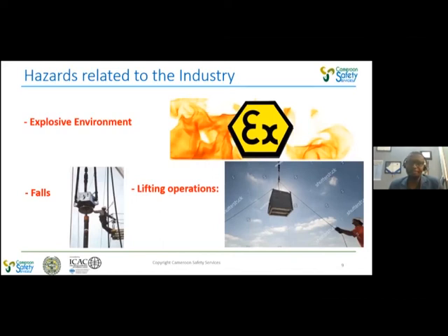And there are stairways which you have to move overhead, and there are things like maintenance on the crane. These are some of the activities that require people to work at height, so it can lead to falls. Even in living quarters where the crew live, there are possibilities of falling down the stairs if people descend and climb stairs without proper techniques such as using handrails, so they can trip down and it could be a fall, either on the same level or at a different level below.